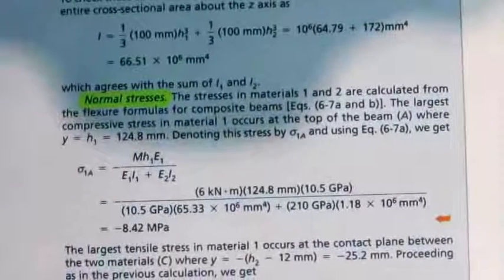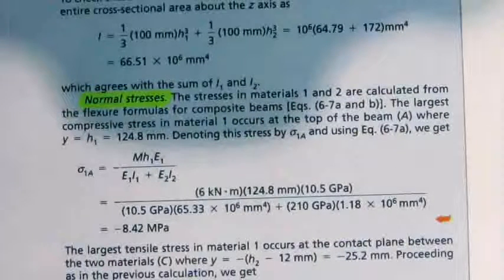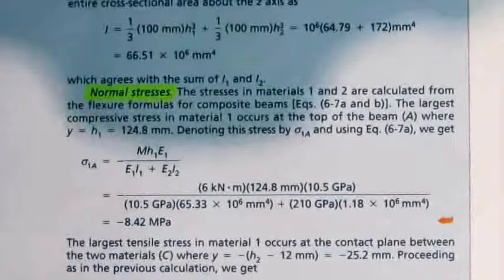we notice that the stress, here's the formula that's given. We've got the moment is +M1, and h1 is essentially the distance that I talked about, from the centroid of that area 1 to the neutral axis. These are the things that we've calculated with the first step. You replace there accordingly, and this side here you replace with E1.